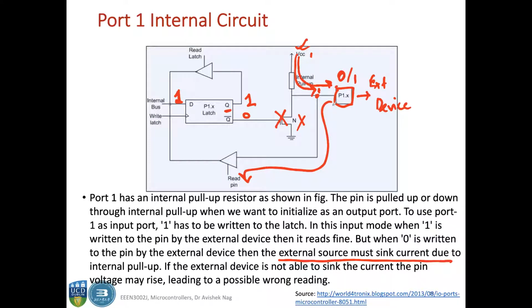Okay, if the external device is not able to sink the current, the pin voltage here may rise and it may lead to a possible wrong reading. Okay, so putting a 1 here can be directly read. Putting a 0 here, there might be a problem if the external device cannot sink this current. Okay.